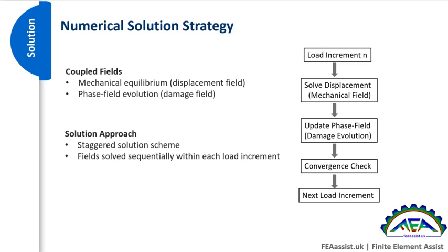So first we apply the load. In the UMAT subroutine, we solve the displacement field and update the phase field. Abaqus will check convergence and go to the next load increment. This will again improve numerical stability and convergence.